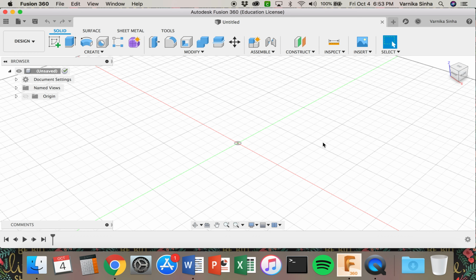How can you do this? There's a thing called orthogonal drawing. So what is orthogonal drawing? The most basic way to remember this is: how does your 3D object look from the front, the right, and the top in 2D? So an eagle's eye view of the object, the front view, and the right view. If you look at it straight on, it creates a 2D image for you to understand how it looks. Based on that, that's how we're going to make our 3D object, by looking at the front, right, and top views.